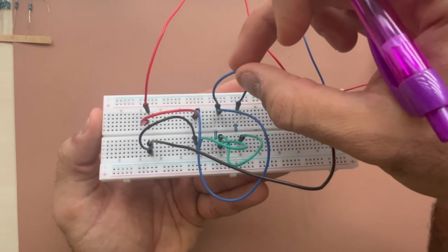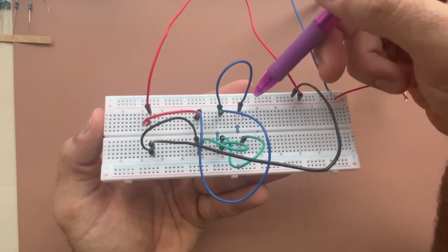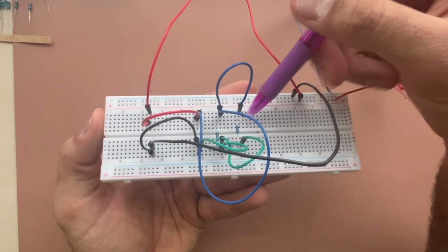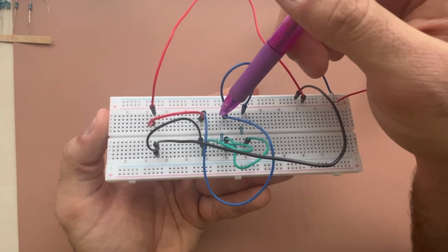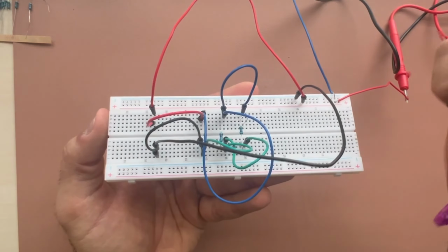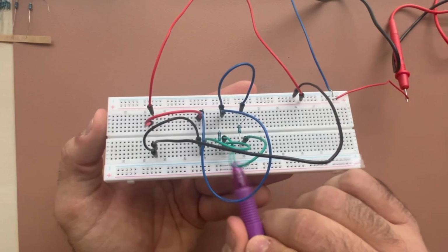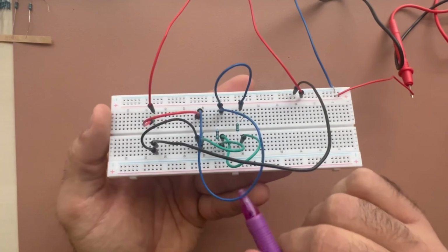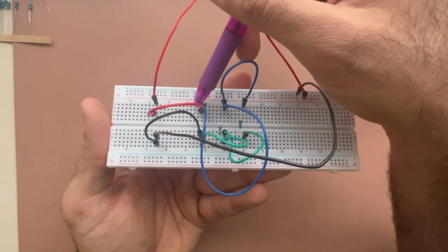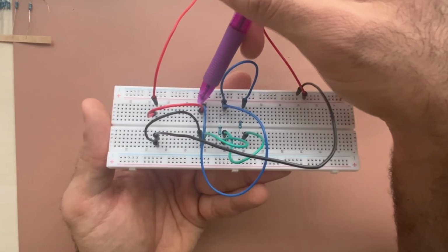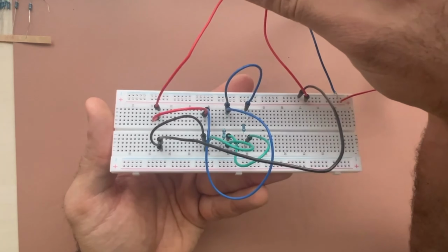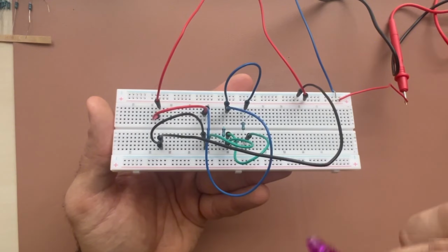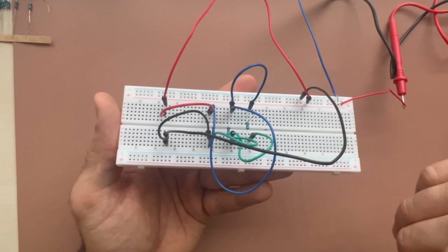As you can see over here, this jumper, for example, is connecting the top side of the 10K to the top side of the 5.1K. Another jumper connects the top side of the 5.1K to the 2K itself. I'm doing the same thing in the middle and for the bottom. In the meantime, I'm going to connect the positive side of the 2K, and they're connected to each other, to the positive side of the source, and the negative side to the negative side of the source. So everything is settled, and let's answer the question.